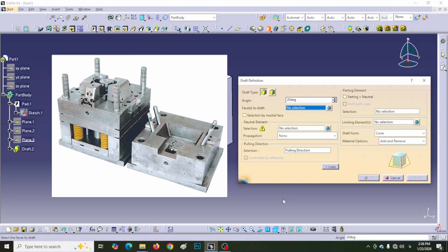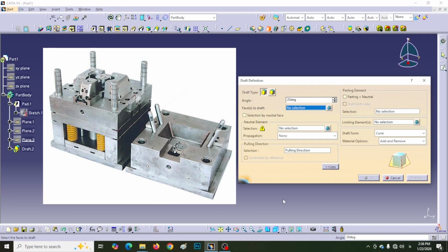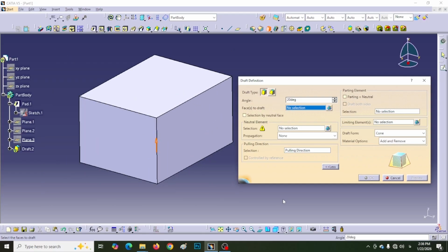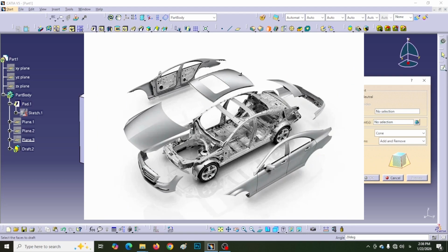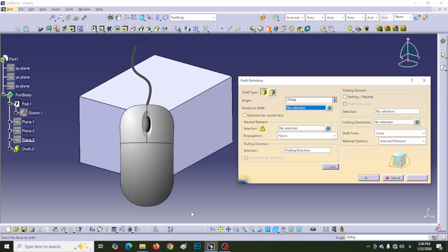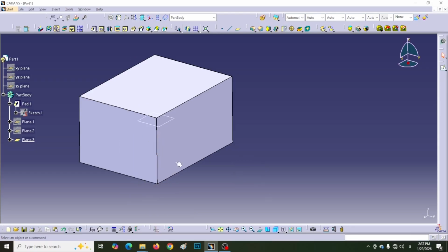This surface is not necessarily parallel to the neutral surface, although in most cases it is parallel to the neutral surface. Even the parting surface can be aligned with the neutral surface. In the design of complex automotive parts or household appliance bodies, sometimes the parting line must go around the part in a broken or curved way due to the specific form of the body.